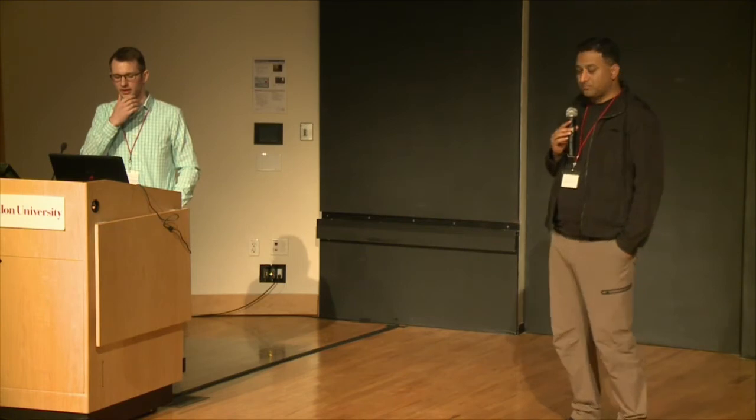Yeah, absolutely. And we've seen several tricks already in the conference with the epipolar scanning type setups. For the scenes that we captured, we diffused the illumination over the scene, and then we had a line sensor that we scanned in a rolling shutter type fashion. But you could also consider different ways of positioning the illumination. If you're just interested in capturing the 3D geometry, you could focus your laser down to a point and scan that. This is more light efficient. You'll be able to image further away because the light is more concentrated.